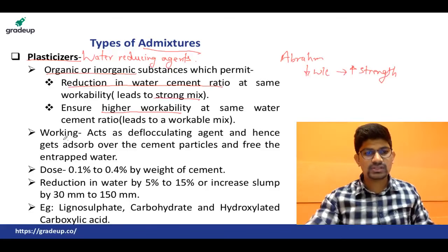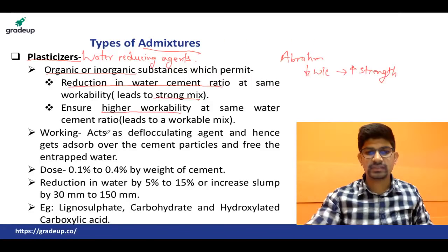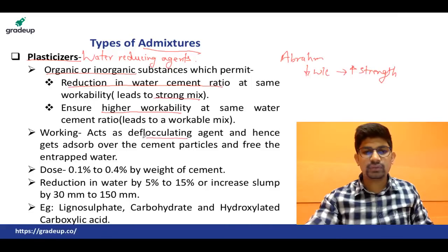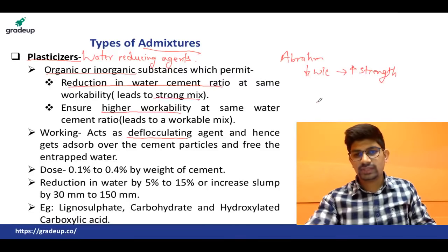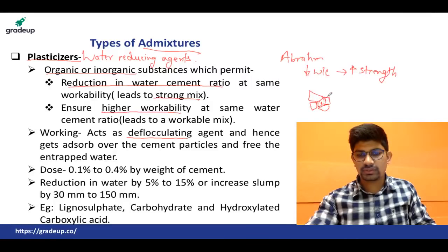Now what is the working, how do these plasticizers help? These act as a deflocculating agent. So if there are some cement particles like this, and there is some entrapped water, suppose this is water, and similarly this is one particle. So there is some water. If you add this, now what happens is they get adsorbed on the cement particles.